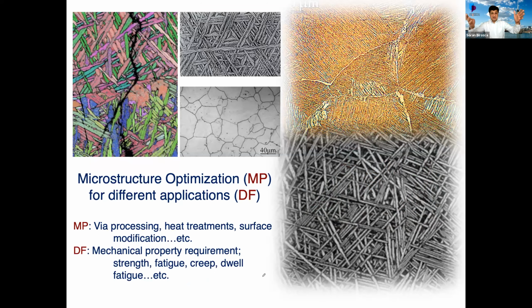As with any teenager, as you see, it is a beautiful microstructure. However, it's been through a horrible time through this growing up stage. Now you will see that's why the microstructure of titanium is very, very pretty. This is a lamellar microstructure. This is what's called Widmanstätten microstructure, and this is work we've done to look at how the crack propagation is going through the lamellar microstructure and so on.